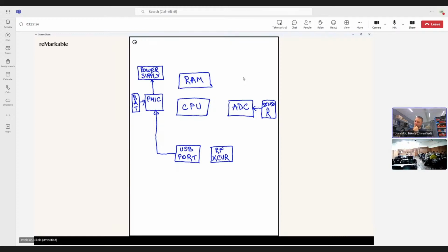But what I forgot to tell you is this transceiver here has an RF front end inside, and it also has a digital part and digital interface. So inside you have circuitry which will put this received data in the digital domain, and you will have a purely digital signal out of this transceiver. That's one thing. I will just tell you that in this domain, for what we are talking about now, I didn't see a receiver or transceiver which has differential outputs. Most probably because it would be a big overhead. Maybe it's not necessary in this case, because the speeds are also very low. So you have plenty of time to decode these pulses.